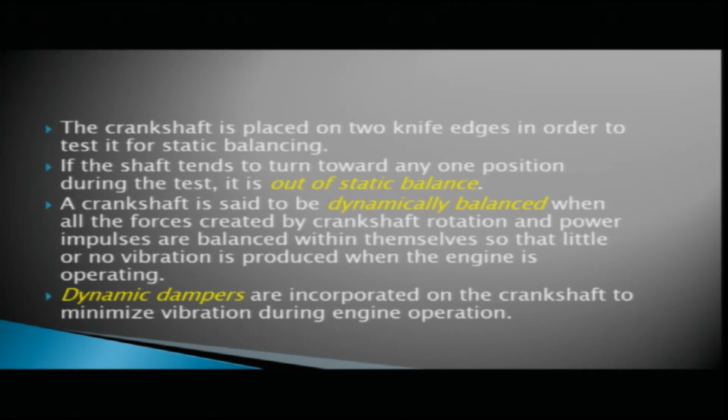A crankshaft is said to be dynamically balanced when all the forces created by the crankshaft rotation and power impulses are balanced within themselves, so that little or no vibration is produced when the engine is operating. In such a condition, the crankshaft is said to be dynamically balanced.